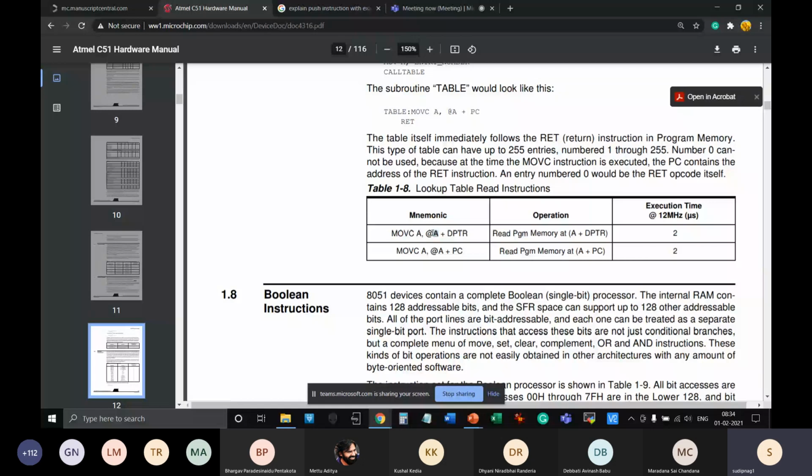If is the maximum value within a 16-bit space or 16-bit address width, because your microcontroller is having 16-bit address lines. So your address is a sum total of dptr plus accumulator, but that sum should be again 16-bit, and whatever the final value comes after this addition, accumulator plus dptr, acts like an address value which comes to the address line of the microcontroller.